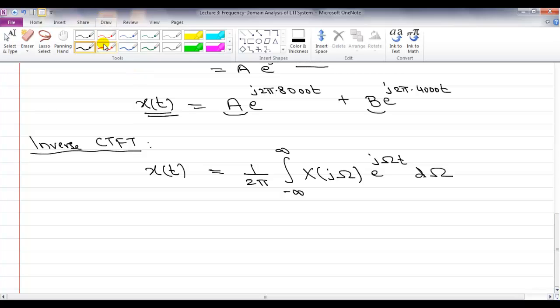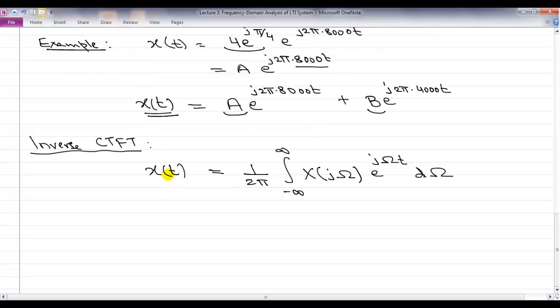So let's try to interpret this inverse continuous time Fourier transform and the x of t that I wrote as a sum of two frequencies. So first of all, what is this integral? Well, this integral, you should really think of it as an infinite summation of very small frequency units, right? Think of the Riemannian sum, how that goes to the Riemannian integral.